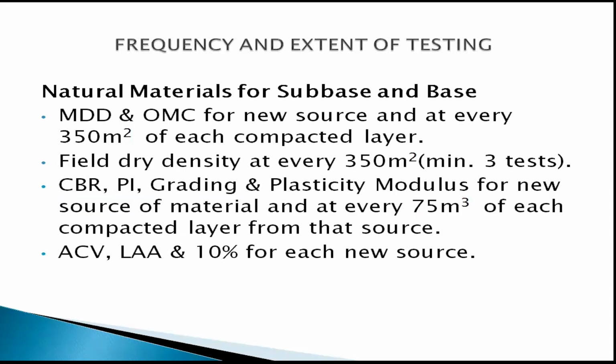We move on to natural materials for subbase and base, as defined under section 12 of the standard specification. So definitely we will do the initial assessment, to take a decision as to whether the material from the borrow pit can be brought to site for use.